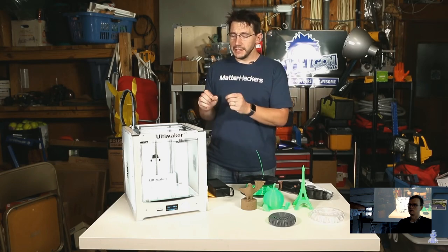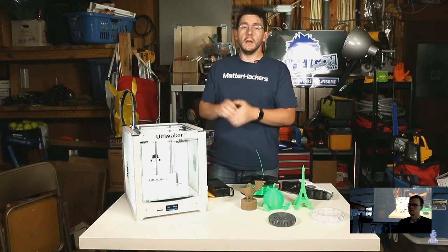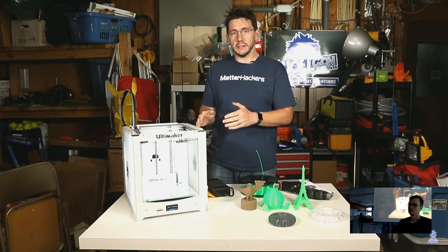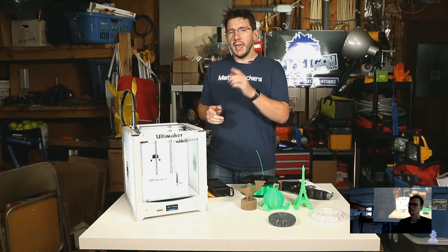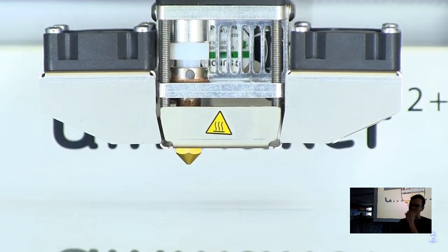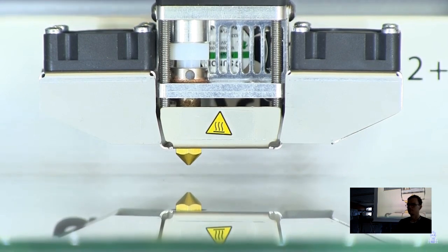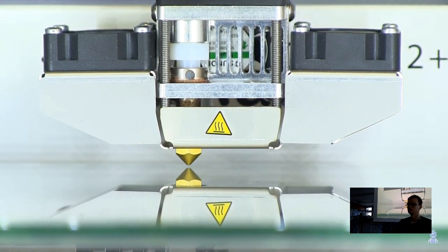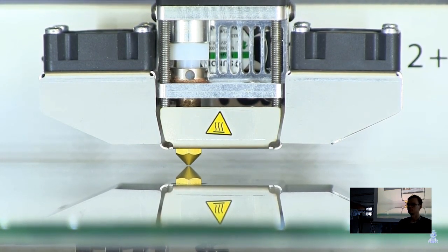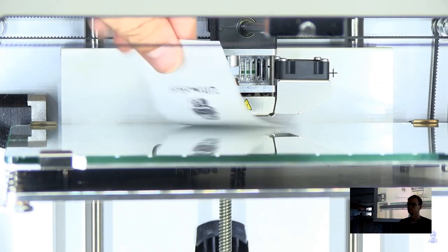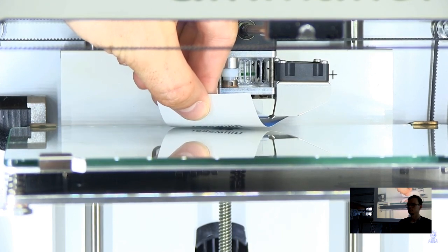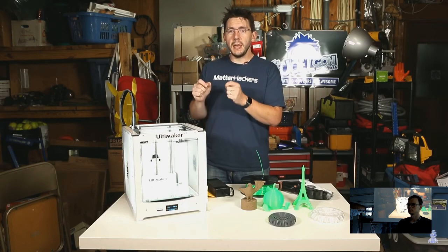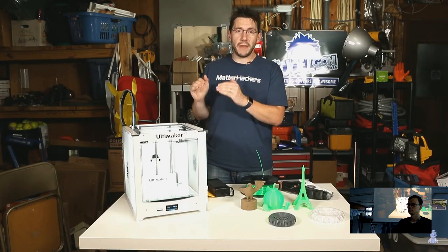All right, I'm going to tell you a few things that I think stand out about this printer. The first one is the assisted bed leveling system. The bed is leveled manually, and there's no automatic bed calibration on this machine. However, the machine tries to assist you in the way it levels the bed, and it's incredibly easy to level this bed. Even if you have to add a BuildTak sheet or a Flex 3D plate to the top, there's no issues. You just perform a few simple procedures, and re-leveling the bed is taken care of. It's by far one of the easiest manually leveled beds I've ever used.